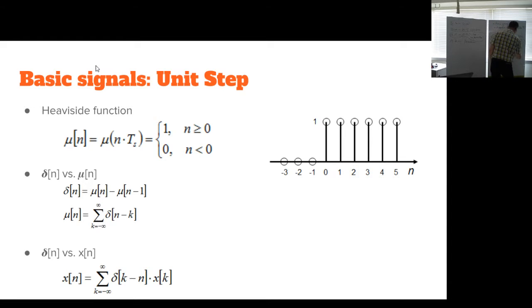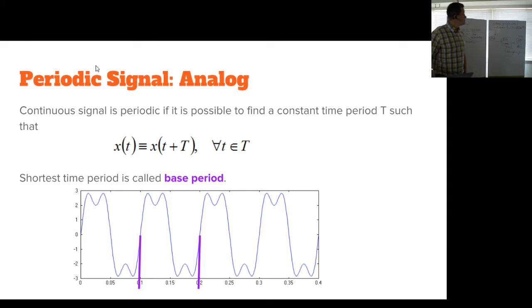If you take the difference, f of n minus the time delayed f of n, what you get is the impulse response. Meaning that, if you have a square wave signal source, a digital sampling oscilloscope, and the data available to some program, you can actually find out exactly what this system does. It defines the whole system. Okay. And then there's some mathematics also about any arbitrary signal, but anyways, let's go forward.